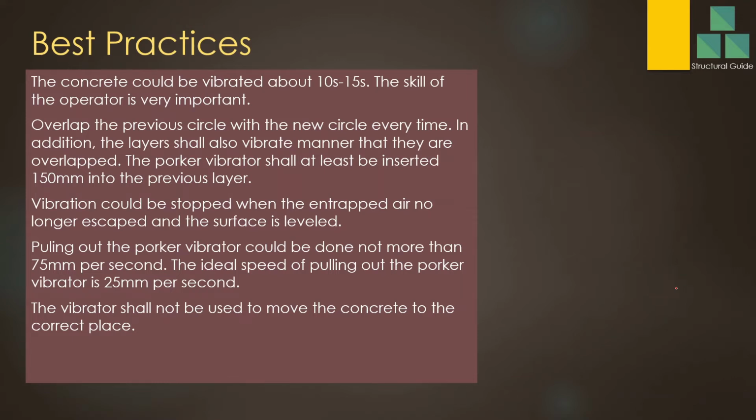Best practices in concrete compaction or concrete vibration. I have listed almost all the things that we need to consider, so you may read this in detail. I will discuss the content I have put here. The concrete should be vibrated for about 10 to 15 seconds. The skill of the operator highly depends on this compaction of the concrete and the quality of the concrete we get after vibrating.